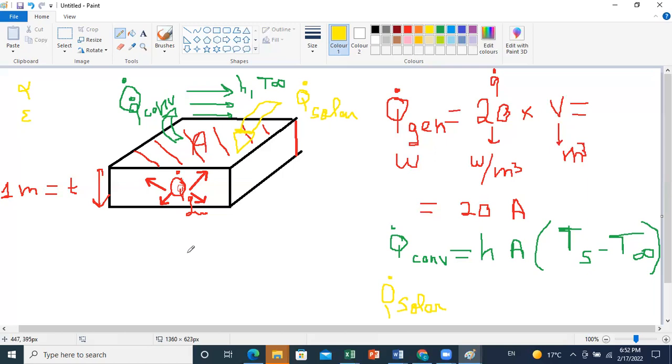When we used the radiation formula, we had two surfaces of different temperatures, and you have a radiation flux from one surface to the other, okay? Here, did they define another surface for you? No. In reality, you have a certain radiative flux, but it's not just an exchange between two surfaces. Any surface can emit, because it has a certain temperature, and will radiate a certain flux. But to consider that it's receiving a radiation flux, you should have another surface opposing it.